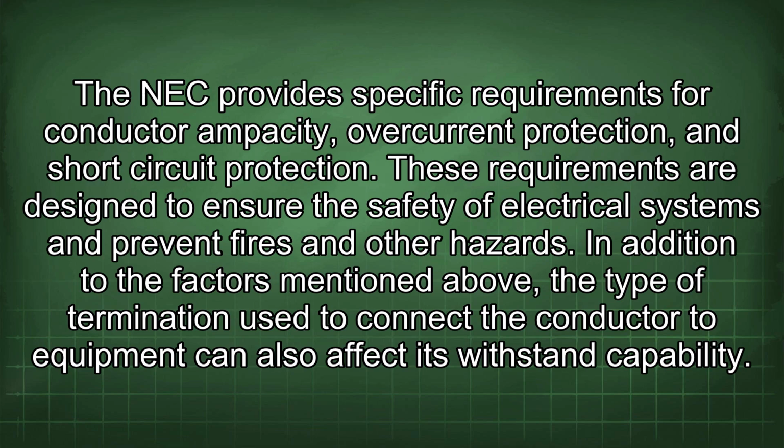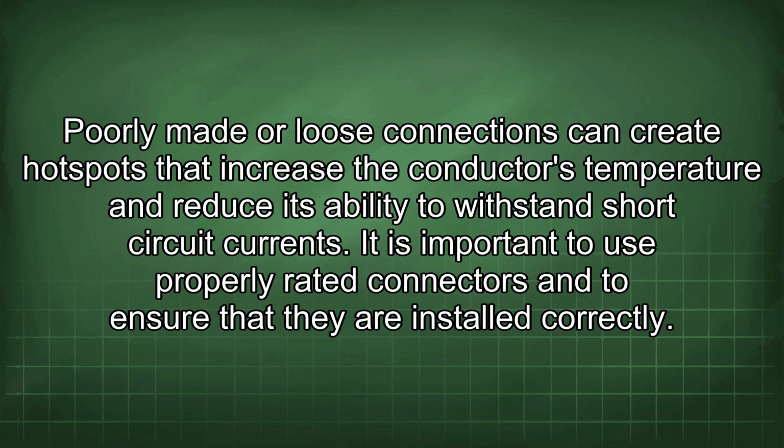In addition to the factors mentioned above, the type of termination used to connect the conductor to equipment can also affect its withstand capability. Poorly made or loose connections can create hotspots that increase the conductor's temperature and reduce its ability to withstand short-circuit currents. It is important to use properly rated connectors and to ensure that they are installed correctly.